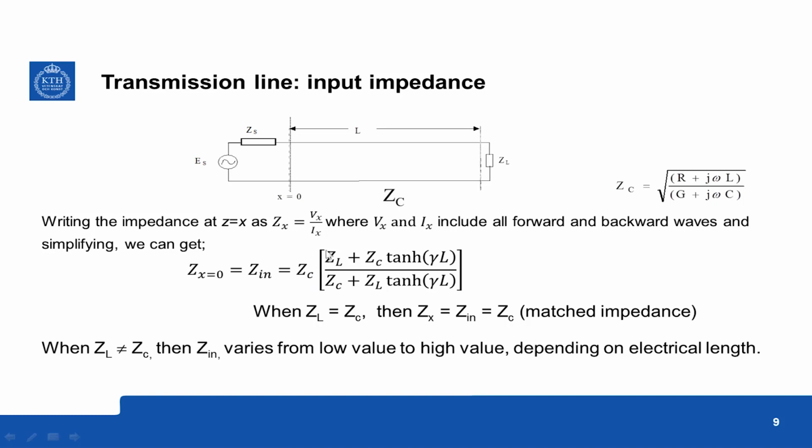That is equal to the characteristic impedance times a hyperbolic function, and this is the propagation constant gamma, which is frequency dependent. So from this expression you can immediately see that they are very similar, the numerator and denominator, except that this L and C are appearing at different places.